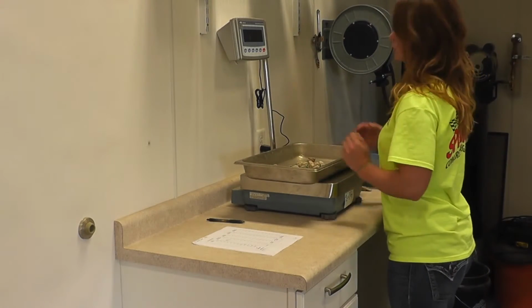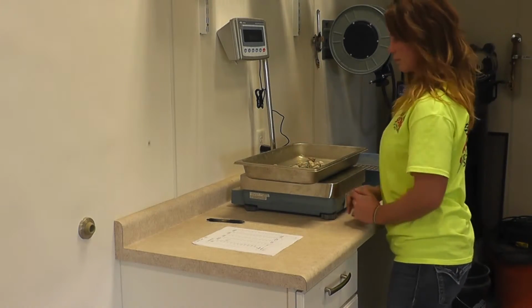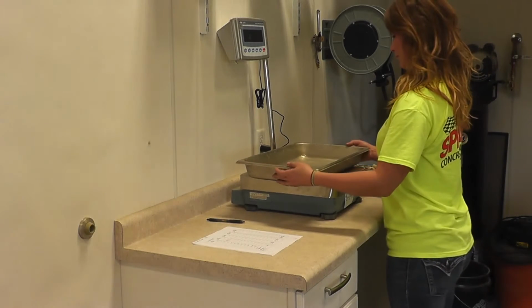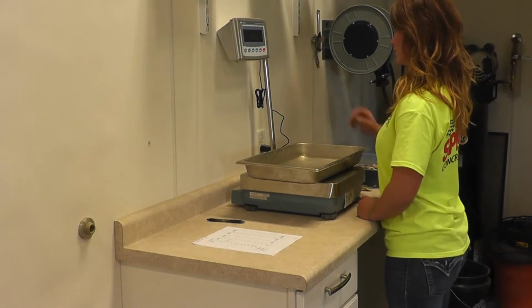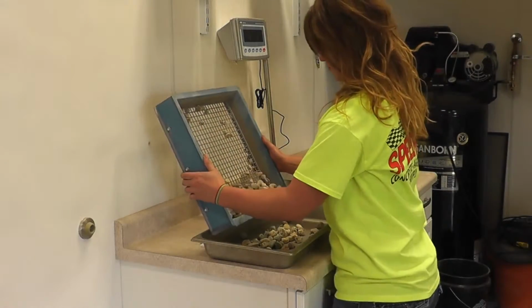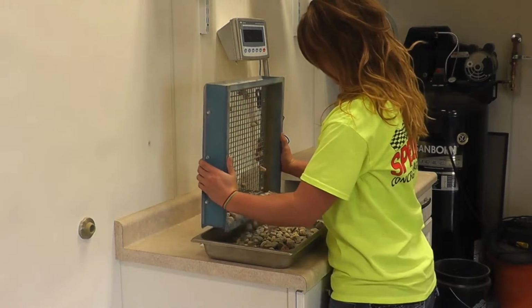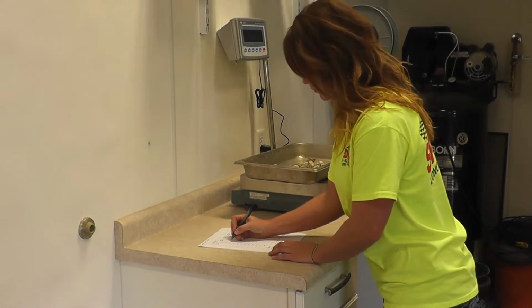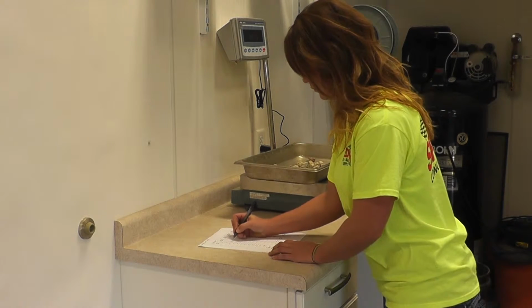Once the material has shaken for the appropriate amount of time, the material on each sieve and the pan is weighed and recorded. Before weighing the material, the weigh pan should be placed on the scale and the tare button should be pressed to a 0 reading or tare weight. Next, the material retained on each sieve and in the pan is weighed individually and each weight is recorded on the gradation form.